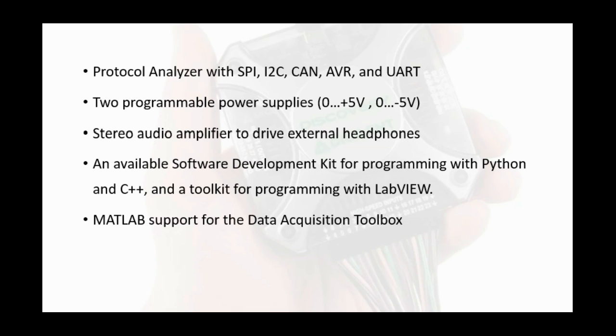It includes a stereo audio amplifier to drive external headphones, so you can connect a headphone to the Analog Discovery 2. It includes an available software development kit for programming with Python and C++ and a toolkit for programming with LabVIEW, for difficult situations where you cannot use the Analog Discovery 2 software, but you can do it with your own Python and C++ programming.